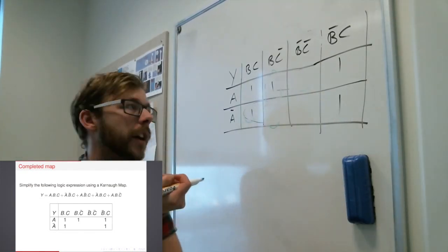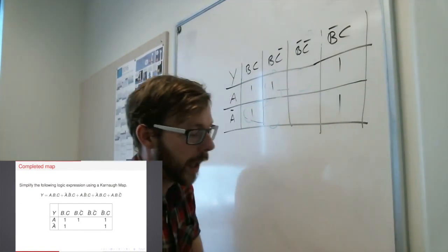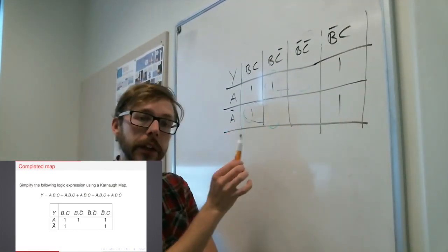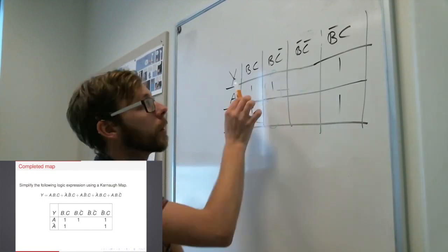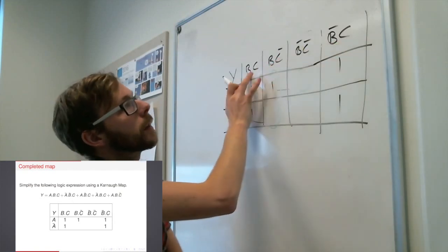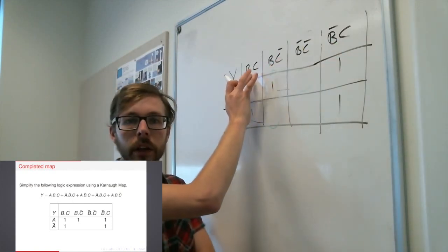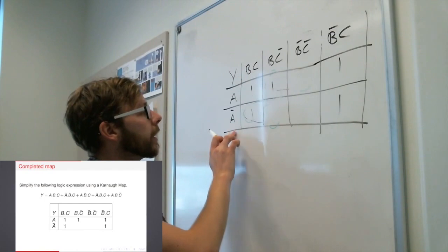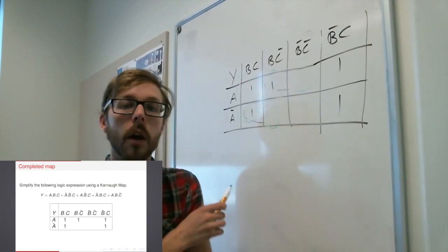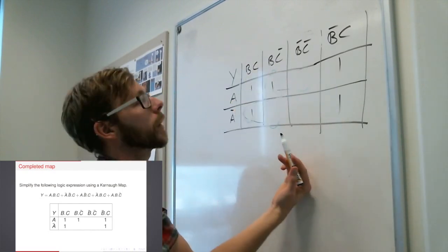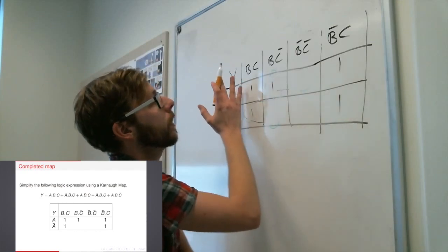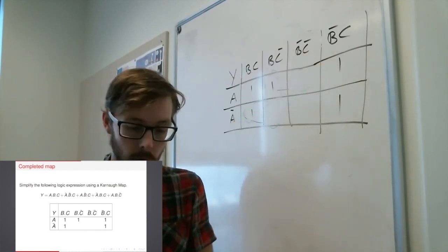Well, one other quirk of this table is that, you know how I was mentioning columns? As you move along them, they change only by one value at a time. They only change one thing. What you notice is that if you go from this column here all the way back to the beginning, that's only one change. And in fact, if you go from the bottom of this table back to the top, that's only one change as well. What that means is that the table wraps round on itself. So my groupings, they're not limited by this edge or the top or bottom edges of the table.